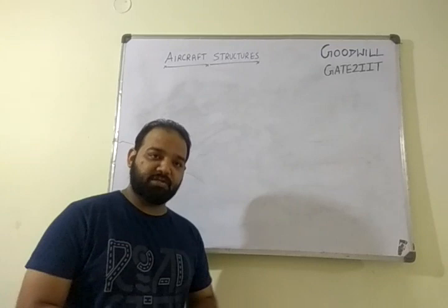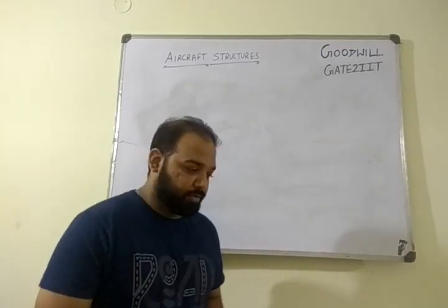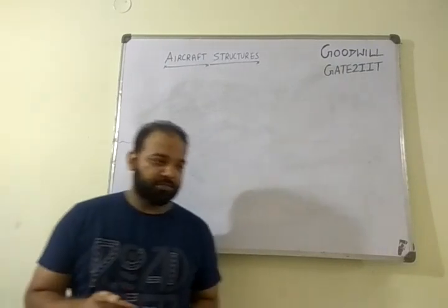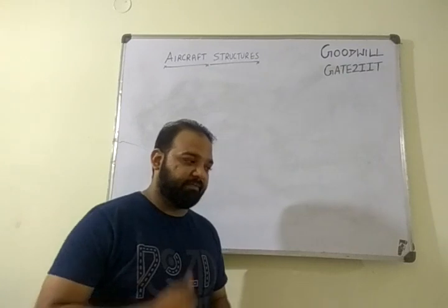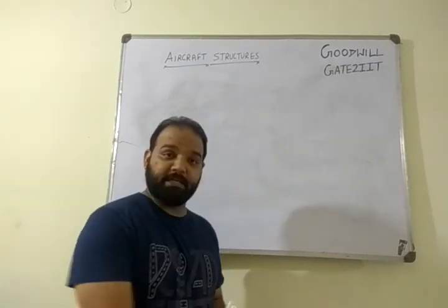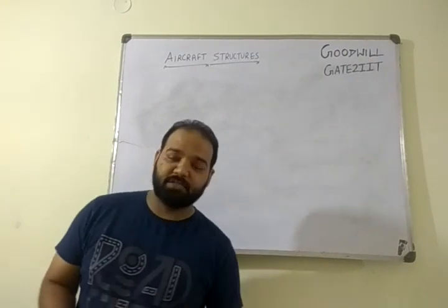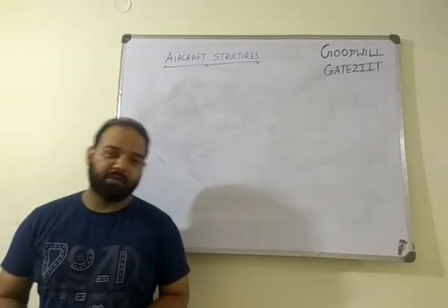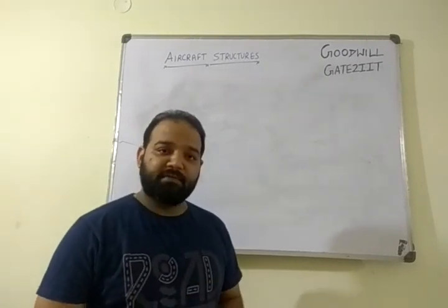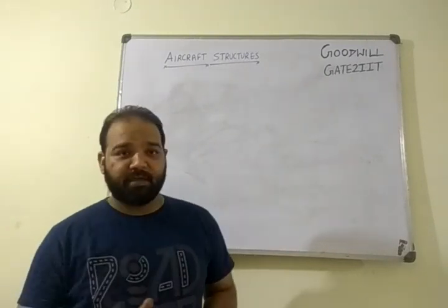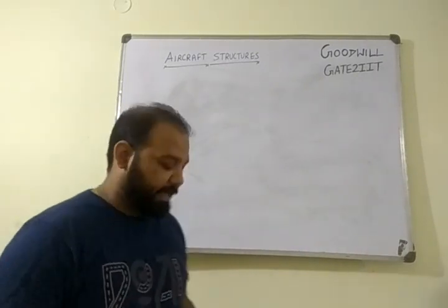Today I'll be focusing majorly on shear stresses in bending in different cross sections. For thin walled sections, we'll be talking about shear flow and shear center. That will be a separate lecture itself. Today we'll be talking mostly about thick walled sections like I section, C section, rectangular, and circular. It is very basic, but a few formulations we need to take care of. I'll be deriving a few things, then we'll try to solve some numericals. For exam numericals, we'll create a separate lecture.